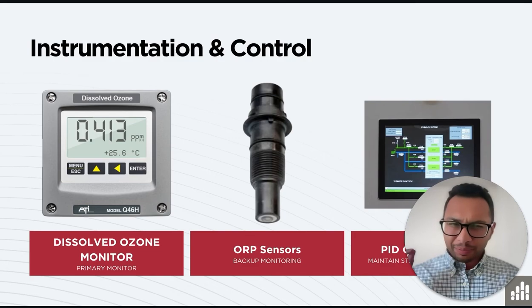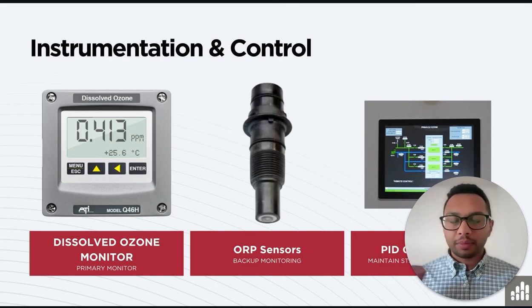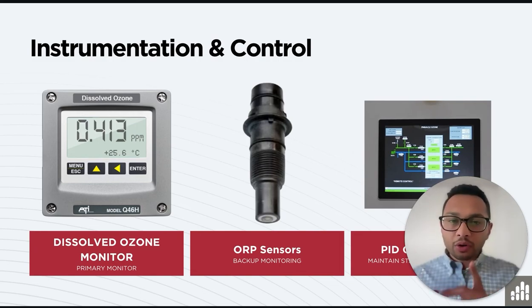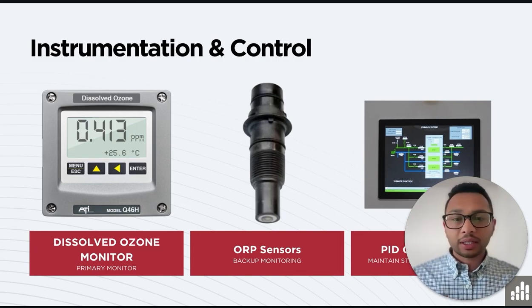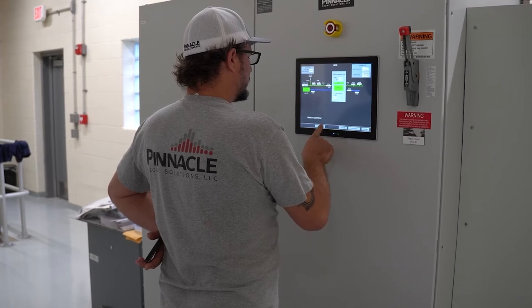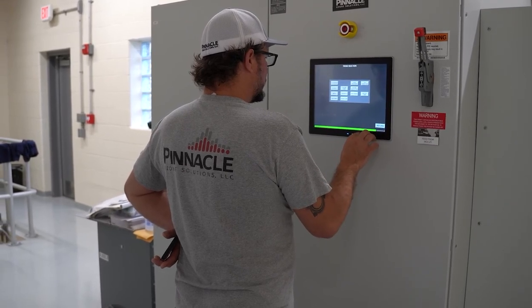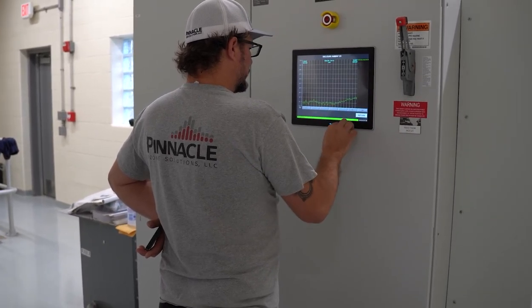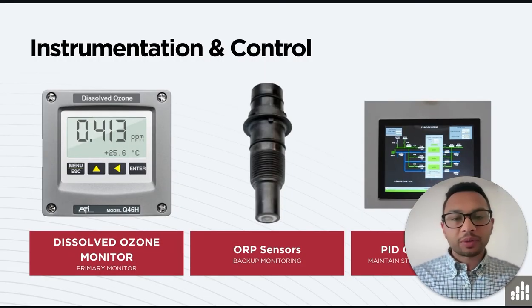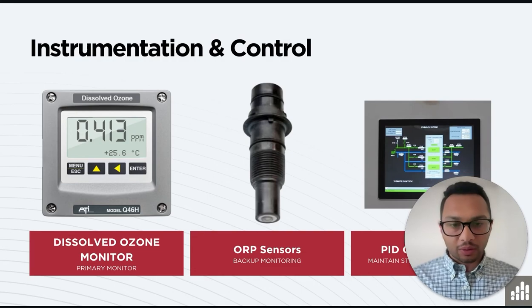Reliable ozone performance depends on real-time measurements and control. The chemistry moves fast, so the system needs to move fast as well. The most important parameter we monitor in the water stream is the dissolved ozone concentration. This tells us exactly how much ozone is in the solution and actually active. We use either a UV analyzer or a probe depending on the system scale and the water quality.